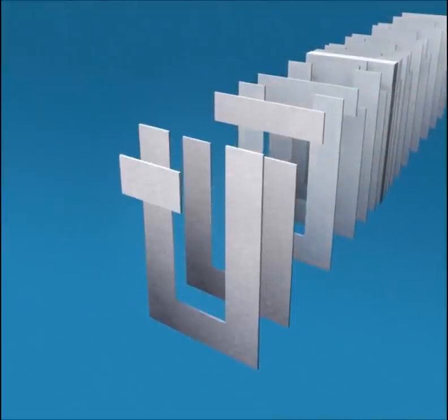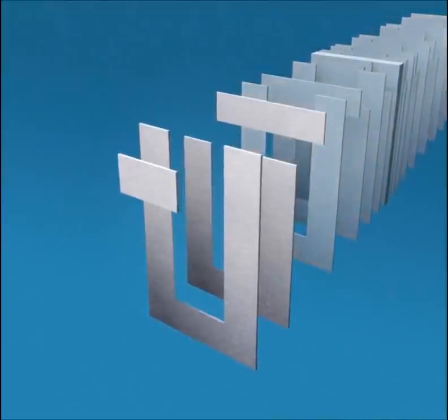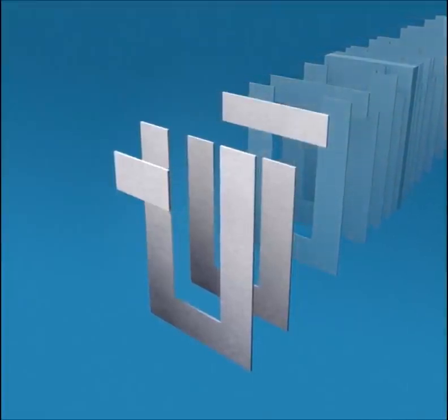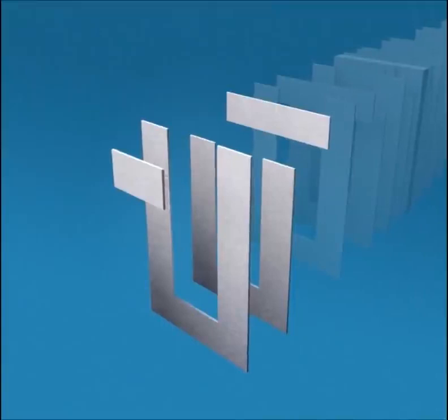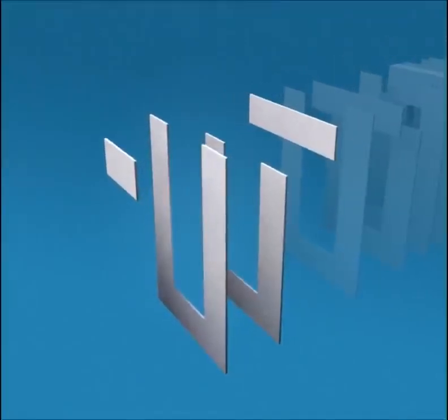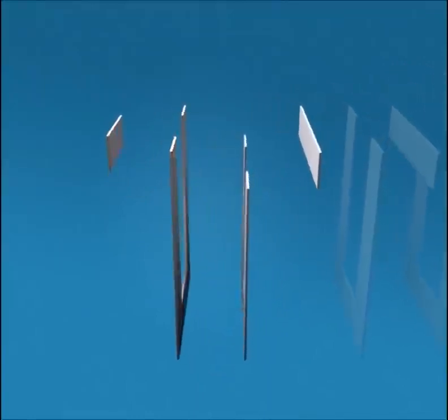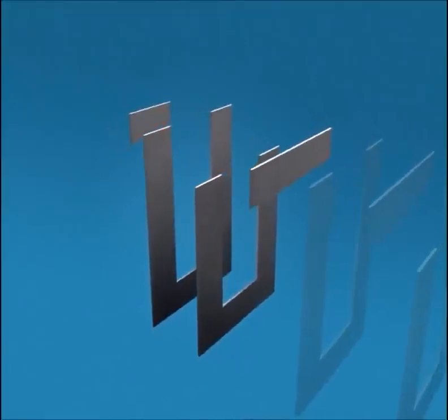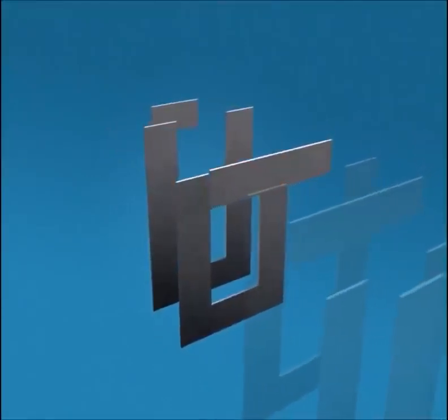The core is used to provide a low reluctance path to the magnetic flux, but the core is subjected to circulating electric currents. These circulating currents, called eddy currents, produce heating and energy losses within the core, resulting in decreased transformer efficiency.